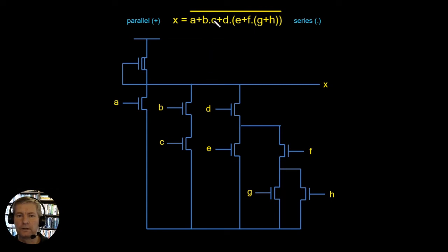Now there's another option here which is a plus, and this plus option here again is the OR, so it brings in another branch. But this new branch here is going to be multiplied by, that is, we're going to be in series with this branch here. But this branch here is going to give us the E, so that if the E goes high, we'll have a path through D and E to the ground, so you can pull it low down through this route.